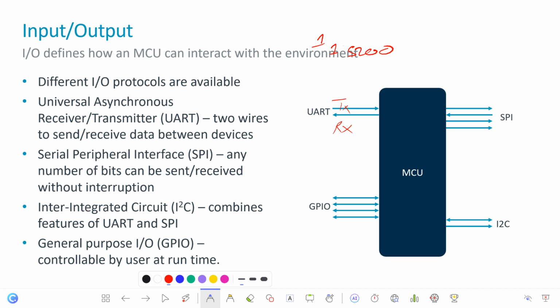We have more sophisticated peripherals that require, for instance, wireless transceivers. Therefore, we go with what? With the SPI to communicate with the MCU. This establishes a master-slave relationship, by which an amount of data can be transmitted in a continuous stream in both directions according to the clock discipline. Of course, those who took digital logic know that through the trigger of the clock, the streaming of the data happens. The data can be transferred without interruptions in a single master single slave configuration.